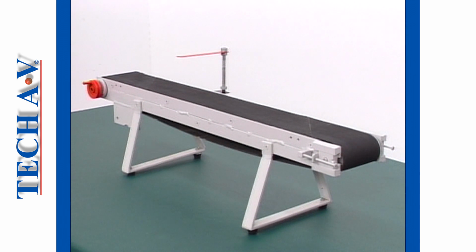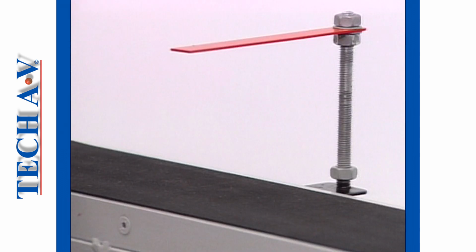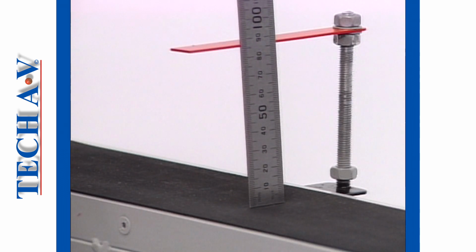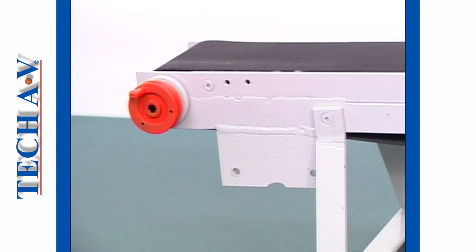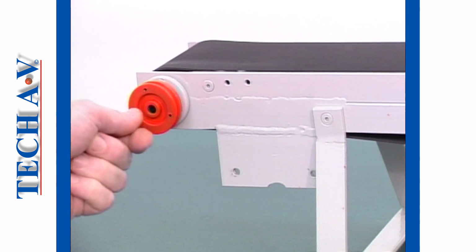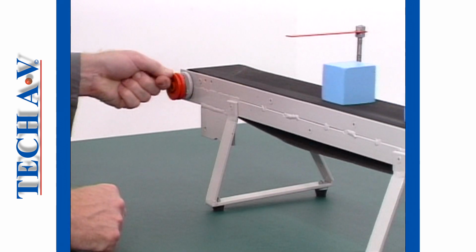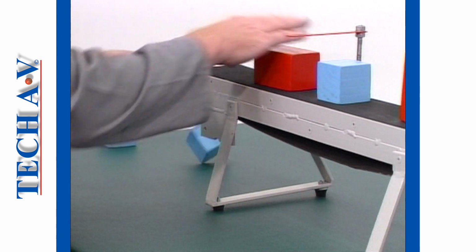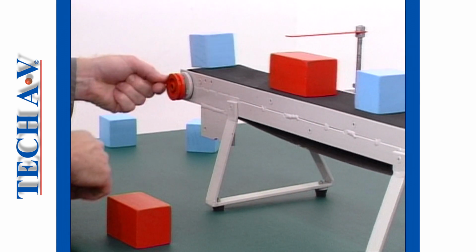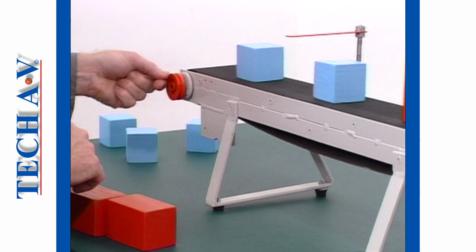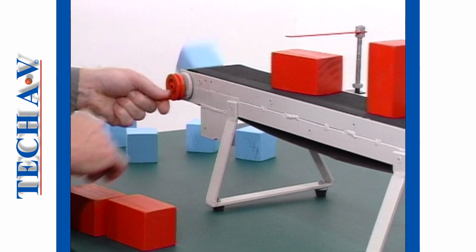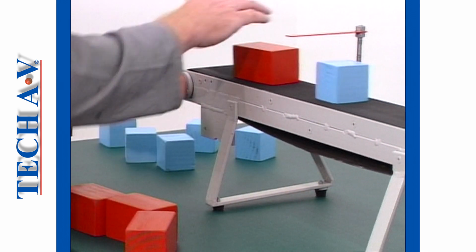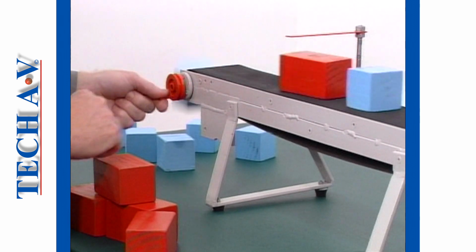Now, applying these fundamentals, a very simple machine could be constructed in order to make the block sorting task a lot easier. Basically, a traveling belt and a mechanical height gauge. By setting the bar to exactly 85 millimeters above the belt and then hand cranking the drive system, any block that is greater or equal to this size will be pushed over by the bar, and the operator simply removes the block and places it in its own pile. Shorter blocks, however, will be unaffected by the bar and pass through to be placed in their own pile.